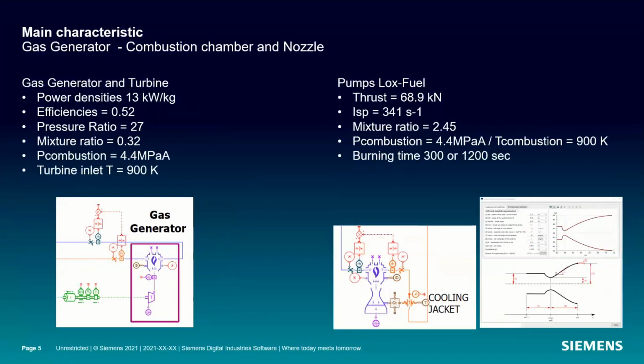So the gas generator, right? As mentioned before, we had the electric driven and then the gas generated. So we knew the different gas generator and turbine level densities and the efficiencies. We knew that there was a specific pressure ratio to it. And again, this is all from literature and references to different white papers in this study-level analysis. But that's what we have, a liquid propulsion library where you're able to model different turbines, different chambers, and different combustion chamber capability to have this level of fidelity in modeling this design.